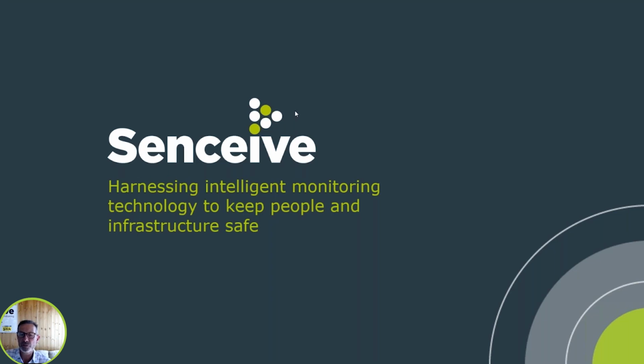So yes, it's definitely possible to integrate things like IPIs and piezos together with things that look at movement in the form of tilt sensors. A lot of our slope monitoring, which is a major application at the moment, will be looking at both movement using tilt sensors together with geotechnical data, subsurface data from IPIs and piezos.